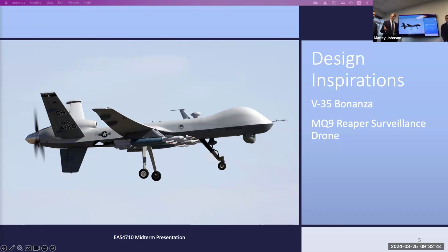And we have also put a lot of thought into what you said about the CG being too far back. The main way we're going to mitigate that is moving the wing back. And we do also have a relatively heavy battery that we can step very far forward. So yes, there's a lot of availability for movement to control the CG. Yes, because what happened in the previous semester was that they had the motor and pushed the battery way forward around the motor. Still they had the CG issue. So well, we'll see in the first test flight.